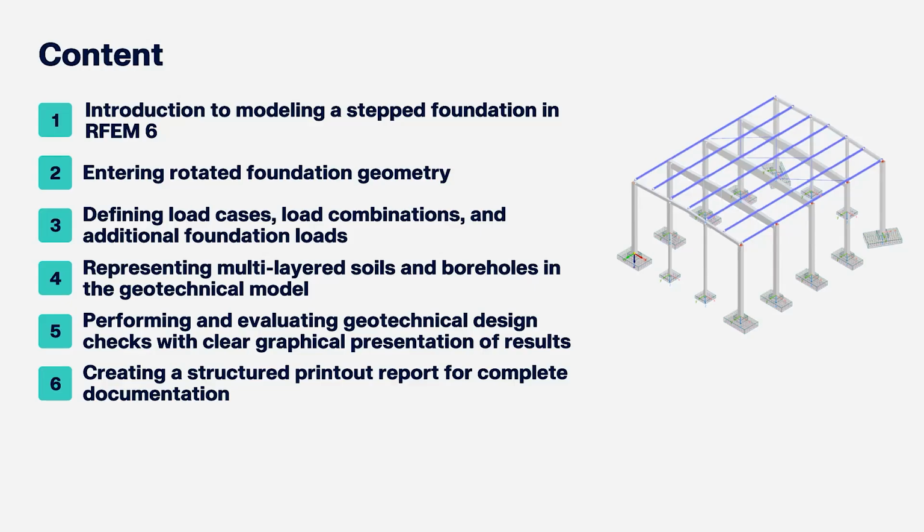Then we'll see how rotated foundation geometries can be modeled cleanly and efficiently. And after that, we'll define the load cases, the load combination, and the additional loads that act directly on the foundation. And next, we will focus on the soil and show how to model a multi-layered borehole.